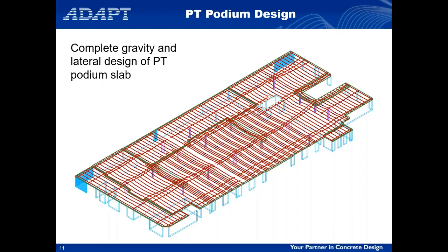It's not in the slides, but I do think it warrants raising this point. There's always the question of what boundary conditions you should consider. Keep in mind that when you're running the program in Floor Pro mode to design the podium, it defaults to a rigid roller, which means that the columns and walls below this image can develop a moment at the end, but they are not restrained in the XY horizontal plane. So as you're applying post-tensioning, all of that post-tensioning is allowed to go into the podium deck. None of it is really being lost in the stiffness of the foundation below.